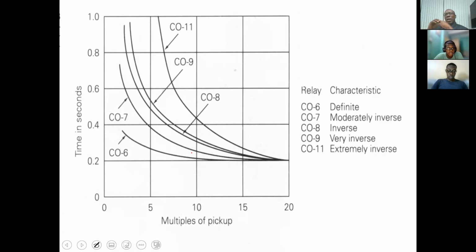And so you wouldn't want to have like the CO7 operating with a fuse because in terms of timing and in terms of ensuring that there is some amount of coordination between them, you want to have the operating curves quite similar. All right. But again, don't get overly worried. We'll come back to these operations and the various calculations in detail.